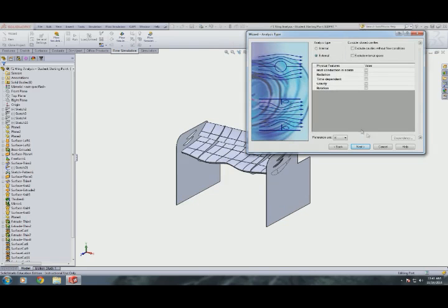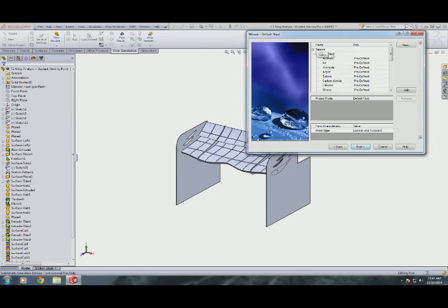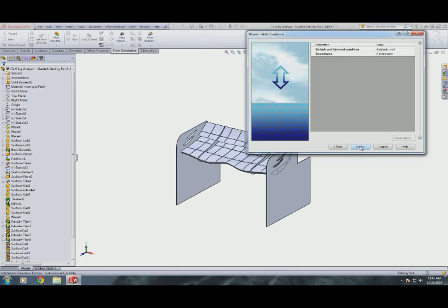Next, gases, air, sure. Change to turbulent only. That hurts the accuracy of the solution some, but anything hitting this wing is probably going to be rather turbulent, and it makes the solution a lot faster. And this is an educational exercise, so we already know it's going to be a little bit wrong. Wall conditions, don't care. Velocity in the z direction.